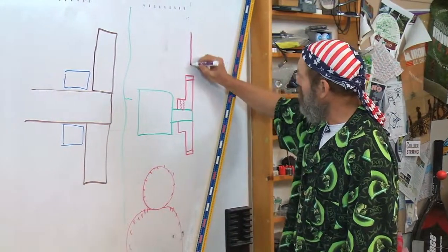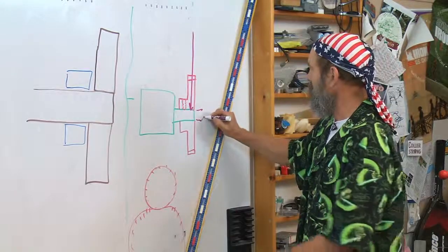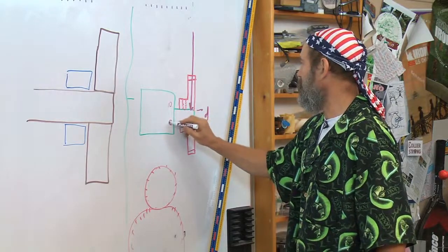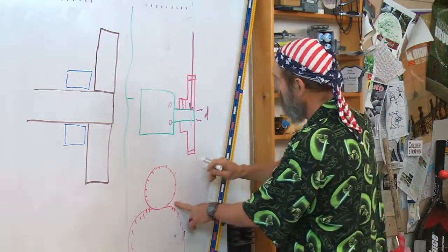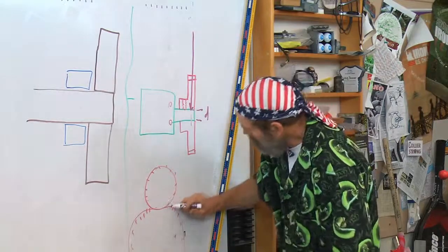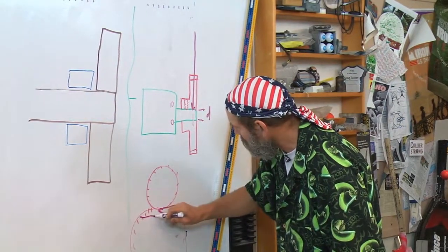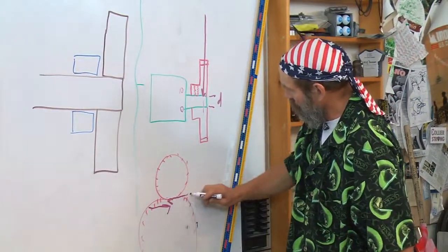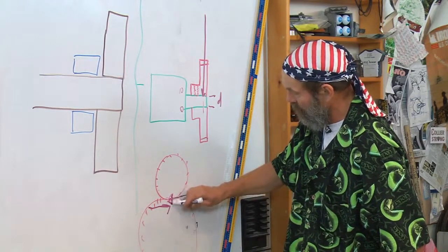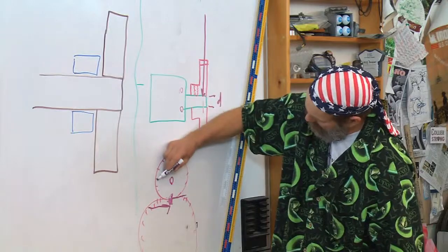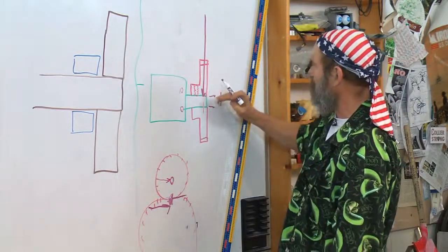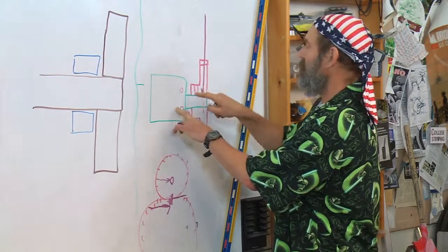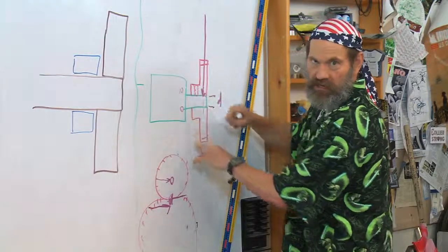Because the forces from the gear teeth come through here. Here's your diameter D. And here's the bearings in the motor. And the forces from the gear teeth, because remember we just did torques? There's a force, action and reaction. Here we are using Newton again. As the gear teeth turn, there's that tooth force from the torque. The tooth force turns into a torque through the gear, through the center of the shaft. That means there's a reactive force through the shaft trying to bend the shaft, applied at about 3 shaft diameters away. And this force from the gears will now dominate the bearings in the motor, and it'll wear it out.